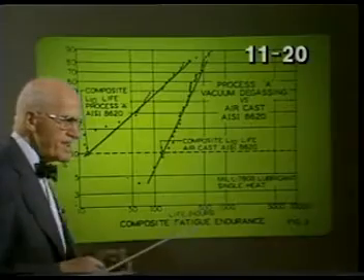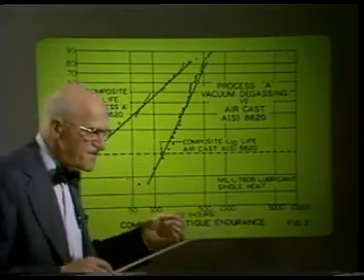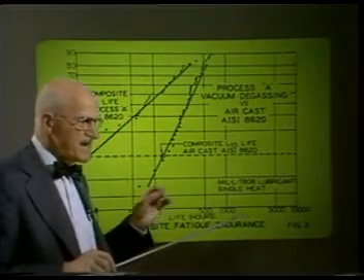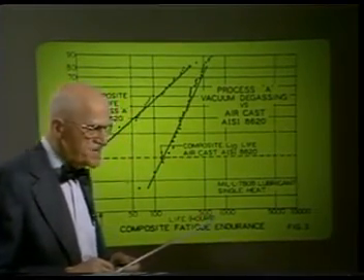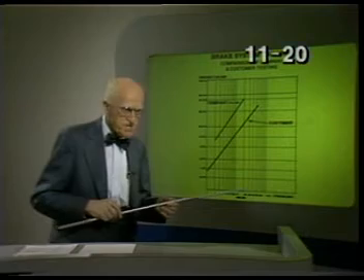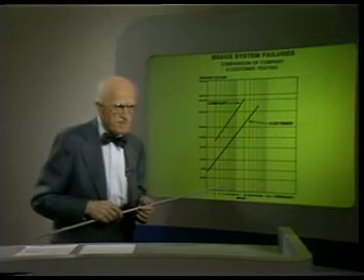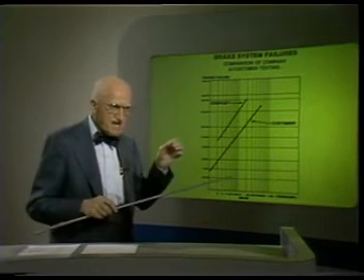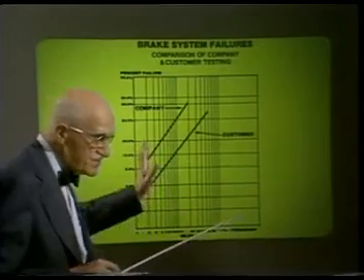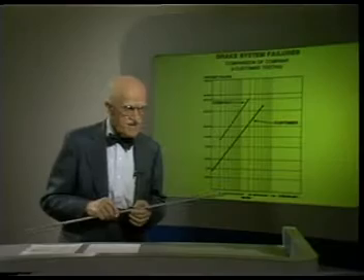An actual case was the comparison of the fatigue endurance of bearings made from two different materials. The two Weibull curves are helpful for quantifying the economics of field performance and thereby for finding the optimal overall cost. A second application was the comparison of the failure rates of brake systems under accelerated tests by the manufacturer versus use by clients. Because the manufacturer's tests lead clients' use by 1 or 2 years, these Weibull curves help to provide early warning of what will be future field performance.